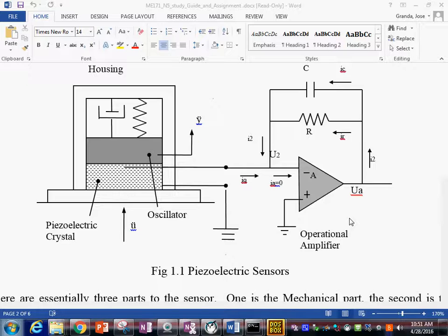So in this case, we have chosen to represent it just as a control source that would amplify the signal. That's one way. Another option would be to use the transformer, and then in the MATLAB file suppress the current. That will work too. However, it will not work on the graphics. So in the graphics, you're going to have some challenges. So the best and easiest way that I found to solve this problem is to represent it as a control source. So that's why you have it as a source of effort, but it has to be only a source of voltage. See, that's why that thing has no current.